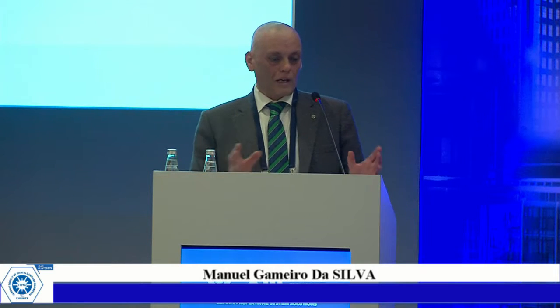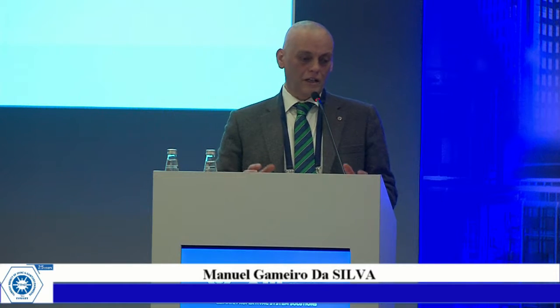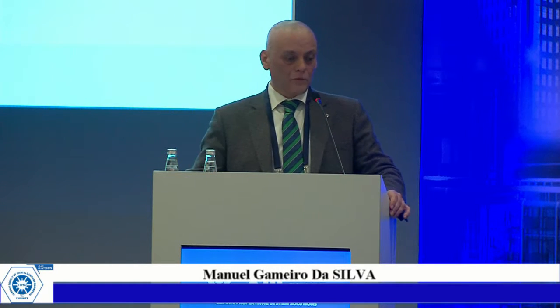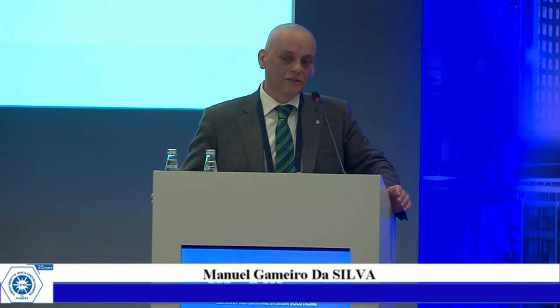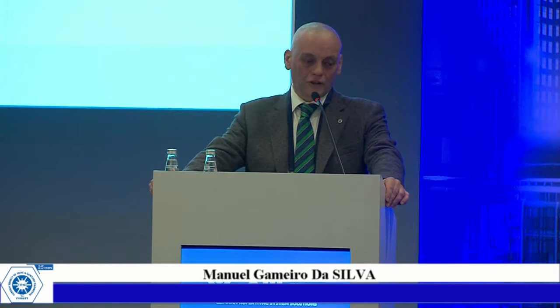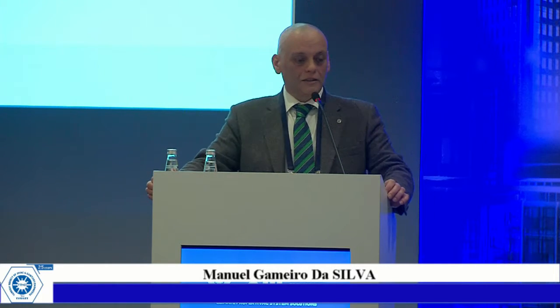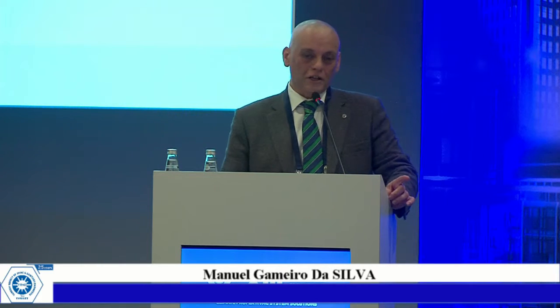And so I put it together with a globe thermometer and with an anemometer. And so we have the possibility of measuring in real time the thermal comfort indices, and even of displaying the building classification.